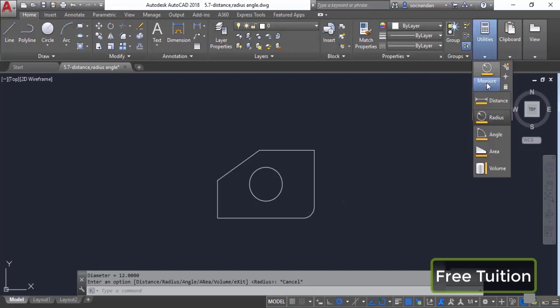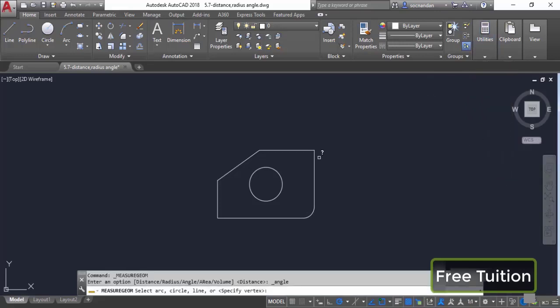So let's now press escape key to get back to the geometry, and now we'll go to the utilities panel and select the remaining options. So the next option is angle. Now when you want to find only the angle of any line, then you can select this command. Now in this case you can select the geometry, and I'm selecting this line, and select the second line or the second geometry with respect to which you want to find the angle. So I'll select this one. And now the angle in between these two geometries is 125 degrees as mentioned here. So the included angle on this side, the smaller side, will be 125 degrees.